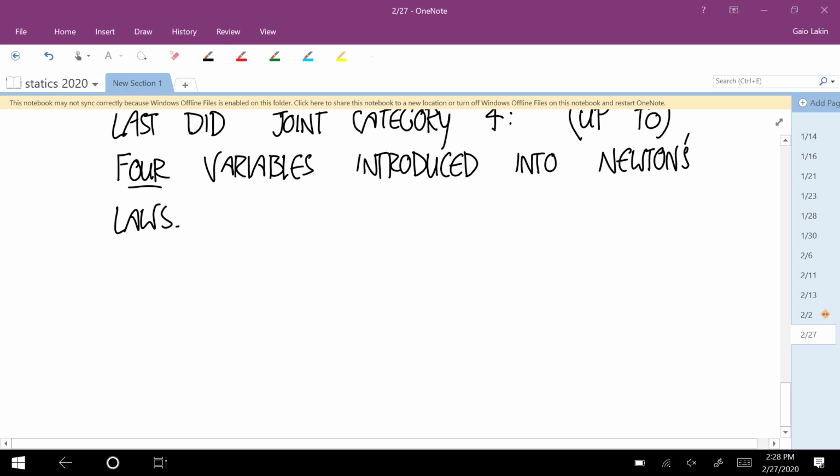And so now we're going on to, oh, and I was gonna say, I said that this joint by itself doesn't allow a rotation like that or a rotation like this, okay? But you wouldn't really wanna rely on this joint to provide big couples over and over again to keep this from doing those rotations. It's the same idea as if you buy a nice door. I don't know if anyone who has kids knows the pain of this one. You buy a nice door, you get it installed, and then you see your kids hanging all their stuff on the doorknob or hanging off the top or whatever. It drives you crazy because the hinges on the door will apply couples that'll prevent the door from rotating down up to a point, but if you keep pushing it, it's going to break.